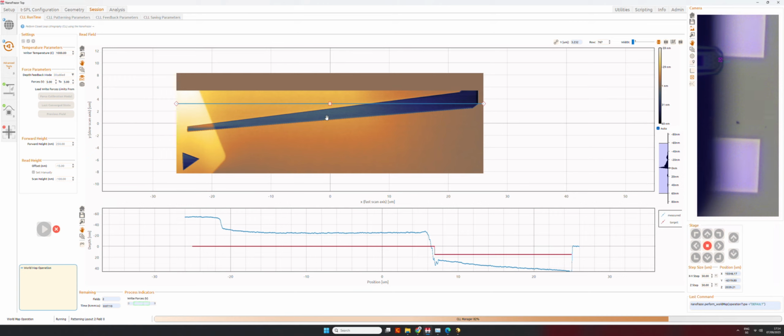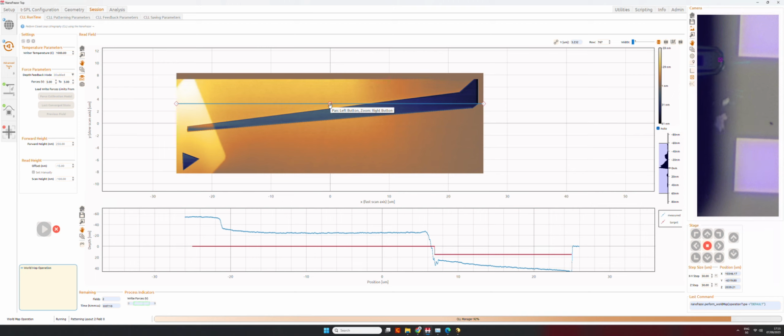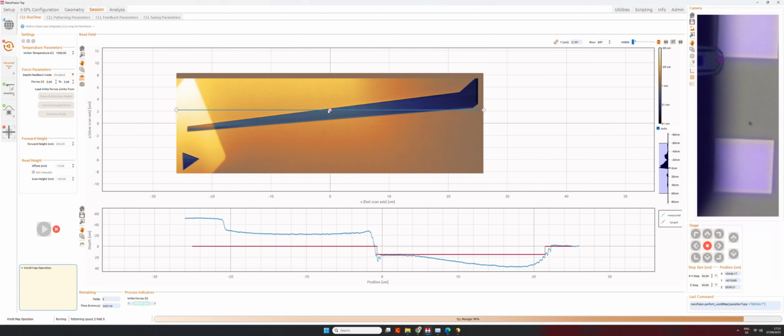One thing that's important to remember is also that when we do overlay, typically we have a bilayer lift-off process. So we're talking about, in most cases, 2D lithography. So that's already one thing to keep in mind. Second thing is that since we're talking about a bilayer lift-off process, usually we have a stack that has either PMMA-MA or PMGI with on top a layer of PPA.